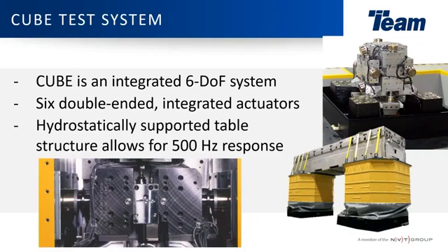By having all of these actuators so closely together, it reduces the oil column resonance and allows the system to get that 500 hertz frequency band, which is more or less perfect for the automotive industry and a lot of lower frequency, harsher tests than what you'd see for mil standard. It can run 810G and other profiles similar to that.